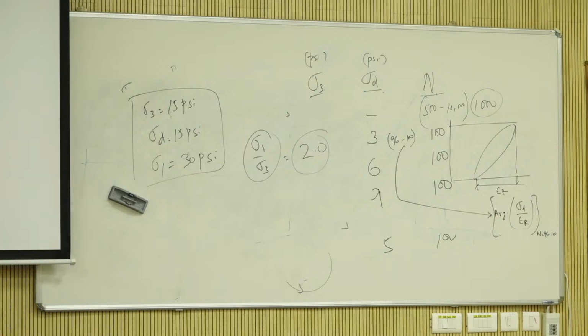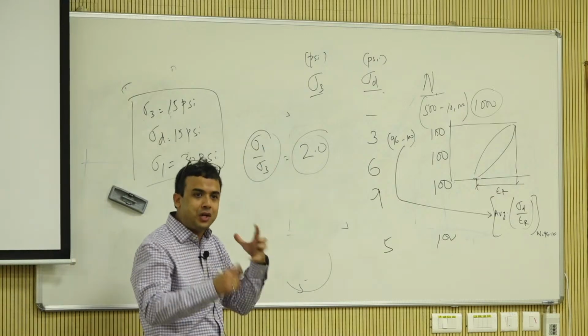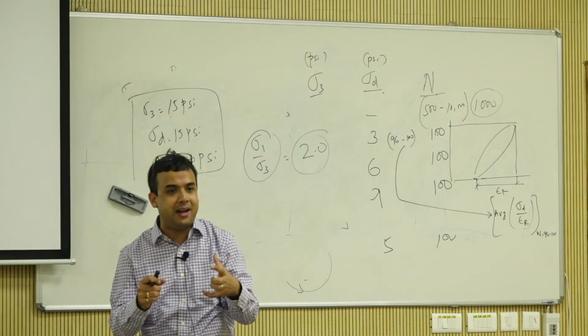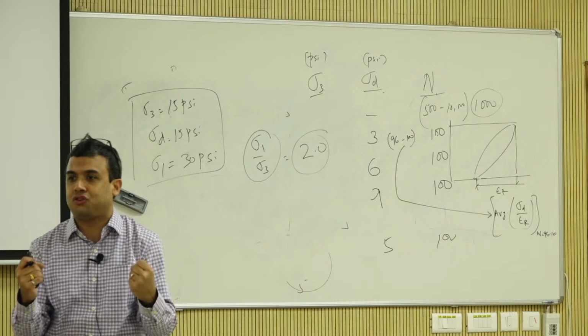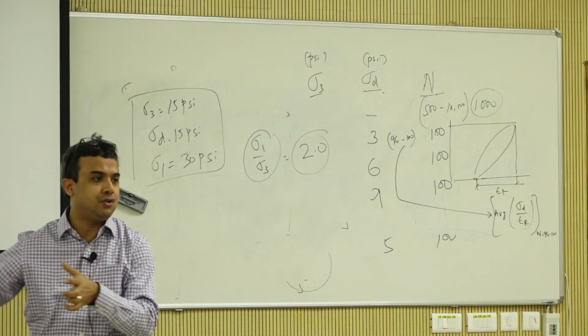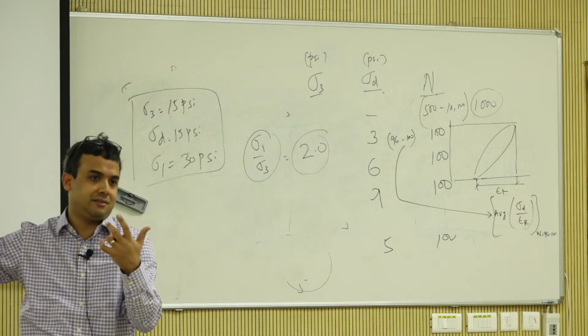If you are trying to shake down a material, if you're trying to get rid of all the permanent deformation and completely rearrange the particles, research has shown that if you do increase this value, it will shake down the material really well, it will pack it really well, and it will become a lot stronger, as long as it's not failing. I mean, you can't apply a ratio of 8. That's going to probably fail.